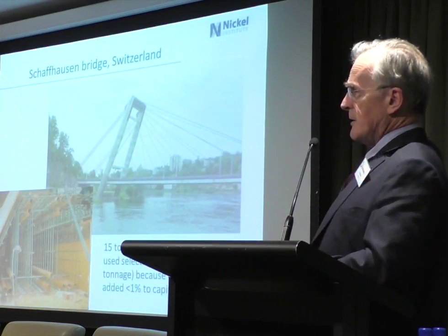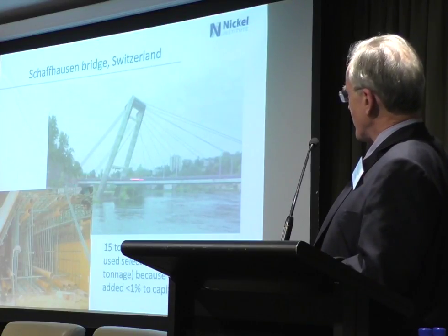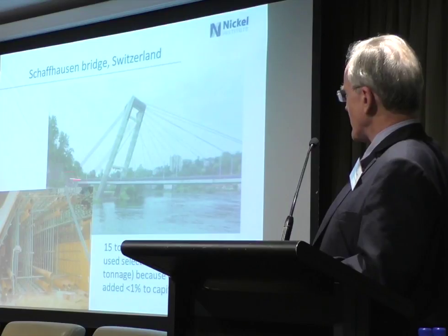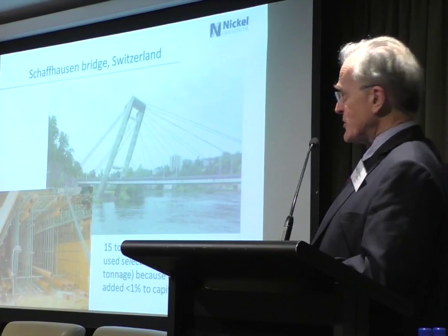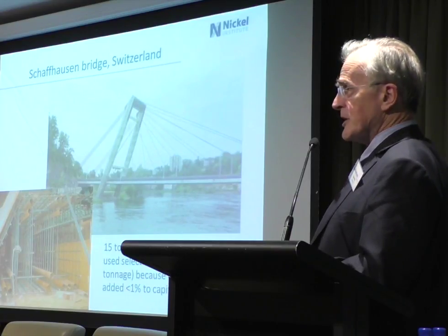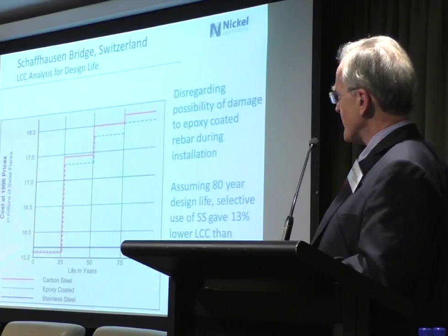This is a bridge in Switzerland, a bridge that suffered from de-icing salts, or was going to suffer from de-icing salts, and they substituted about 15 tonnes of stainless steel reinforcing in it, about 5% of the total tonnage of reinforcement, which added about 1% to the capital cost.